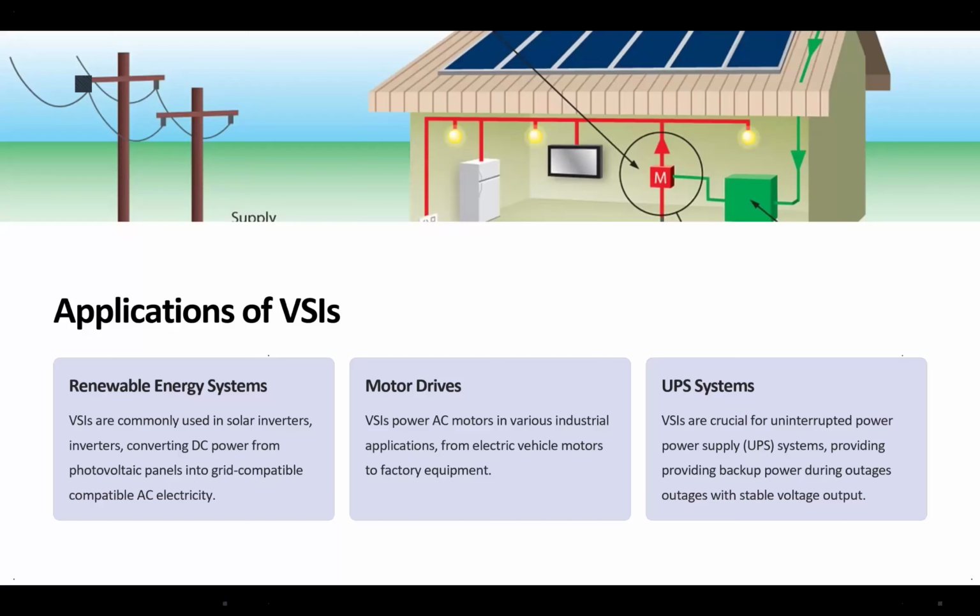One of the other main applications for voltage source inverters is UPS systems. When you want to have control over the energy storages, okay? As you know, the UPS system normally has a battery or energy storage system, and tries to provide an uninterrupted power using an inverter. When the grid is off, you use the battery, or the energy stored in the UPS system, converting it to AC using the voltage source inverter and providing a stable power for your loads.